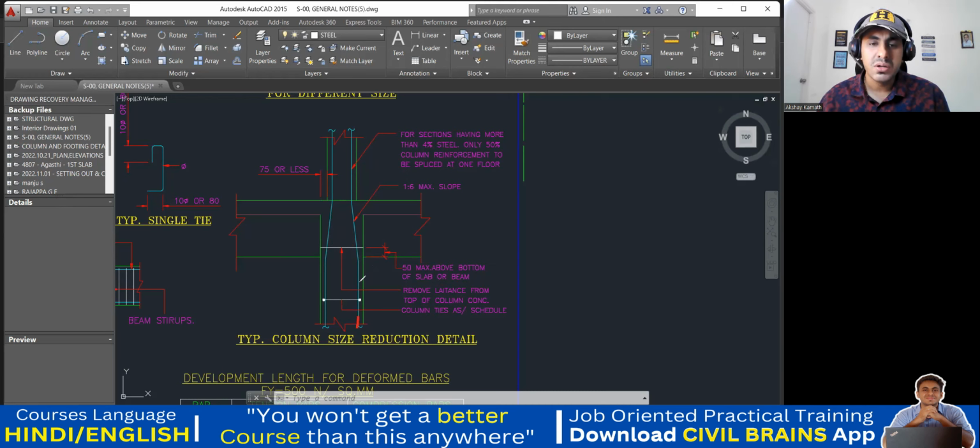That means you bring a bar and give a small bend like this. This bend should be only 50 mm, either from the beam top or the slab top, depending on where you're taking the bend. Okay, and then this 75 or less. This is actually the clear cover. Why is it clear cover? See, this was my column initially, right? Now, since there is a reduction in the width, this has become your column now. Isn't it? Usually in the column, we try to give a cover of 40 mm.